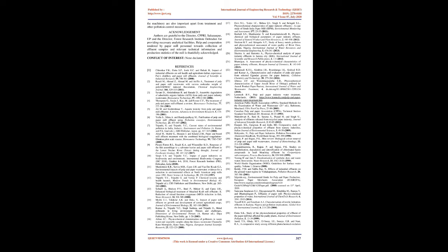33. 7. Determination of BOD. The amount of oxygen required for microbial degradation of organic matter as well as the self-purification capacity of the water body is termed as biological oxygen demand, BOD. It is a measure of the organic pollution load of effluents, thus quantifies the dissolved oxygen levels. The mean values of BOD for effluents at C, E, CB, and CE units ranged from 355.65 ± 3.50 to 1342.22 ± 3.50 ppm. Effluent from CE unit recorded the highest value of BOD, while CB unit effluent showed the lowest value, Fig. 1.